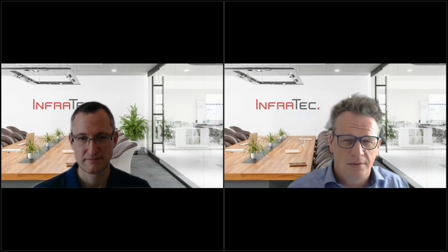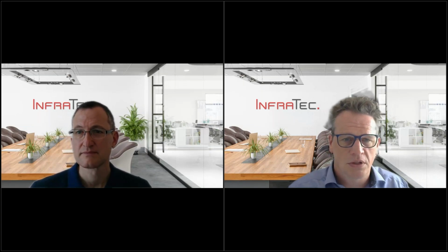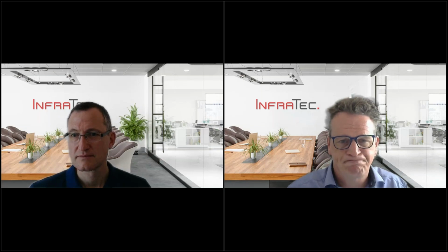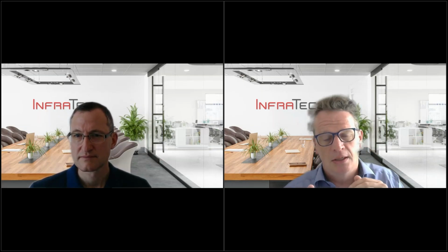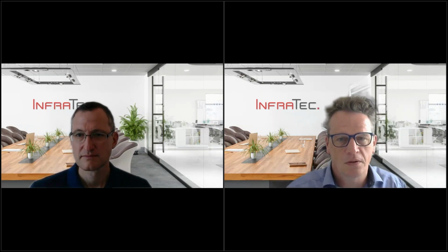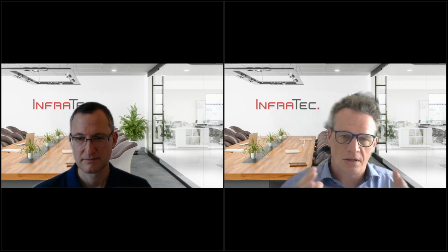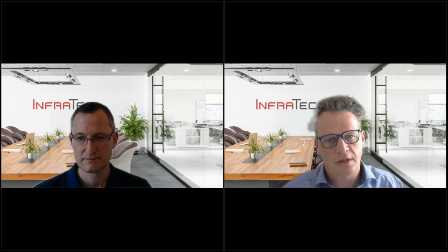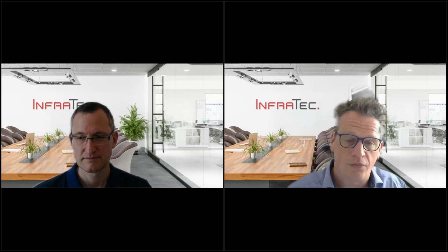If you use a long wave camera, there are different materials used, like gallium fluoride or germanium, for example. But these materials, depending on the measuring task, have some influences depending on their own temperature, for example, that they lose some transmission or other things. So it really depends on the measuring task and the environment you will have. Then you will choose which type of material is the best for the solution.